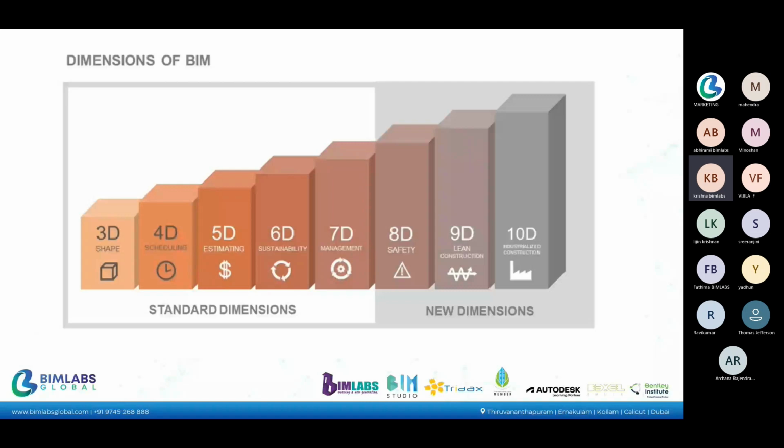Just take an example of one wall. You make different models of that wall, for example 7 types of wall, and you choose different materials and give different properties, everything like iteration, and you do the analysis part. You then choose which wall is more efficient to use in our model while applying different materials and properties. That is generative design: checking the efficiency by creating different models and giving different materials, and choosing the better one from that.